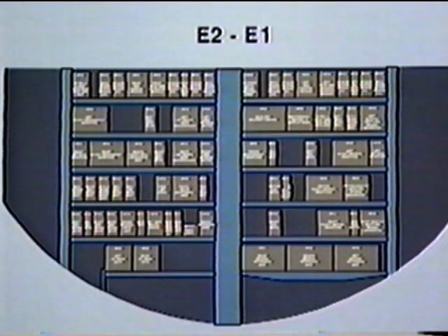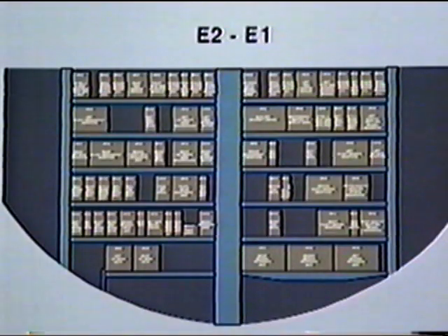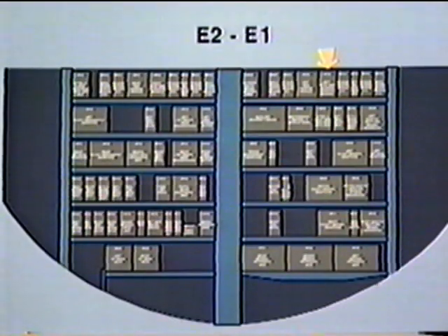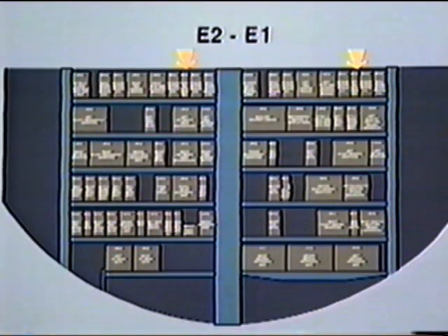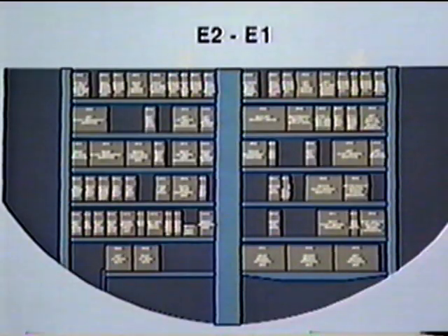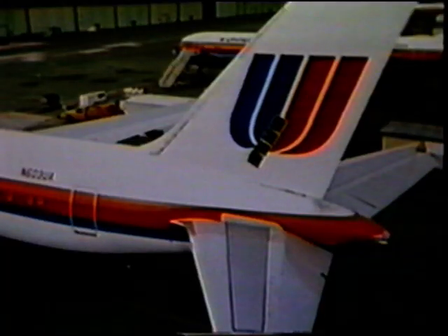Located in the main equipment center are the rudder system electronics components. These include the stabilizer trim and aileron lockout modules, left and right, the rudder ratio changer modules, left and right, and the yaw damper modules, left and right. Located in the stabilizer compartment just forward of the horizontal stabilizer are elevator and rudder shutoff valves. These are accessible through the lower service access door.